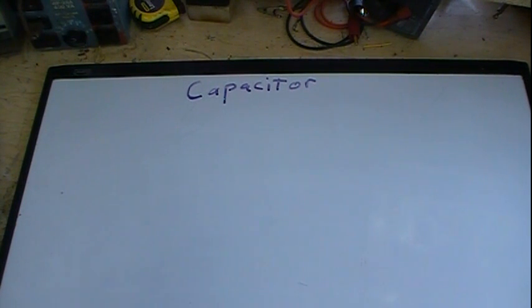You can look up the specs on this: do either a dielectric breakdown voltage or dielectric strength search on the internet, Google it, and you'll find all kinds of numbers. The voltages I give you are per thousandth of an inch of thickness.